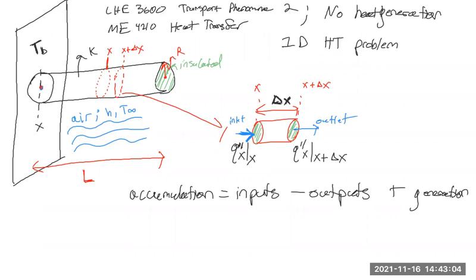And let's say in this problem, we are cooling down this fin with air. So how do we describe the heat transfer happening on this surface? So first, you have to ask yourself, what is that surface? How do you describe that surface area? And the outer surface area of a cylinder is, if you remember, 2 pi times the radius times height. In our case, the height is delta X. So we're going to remember that.